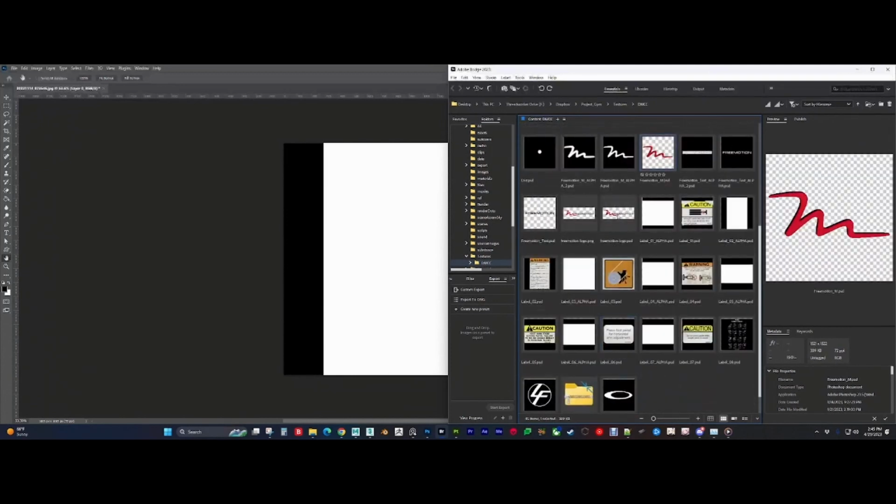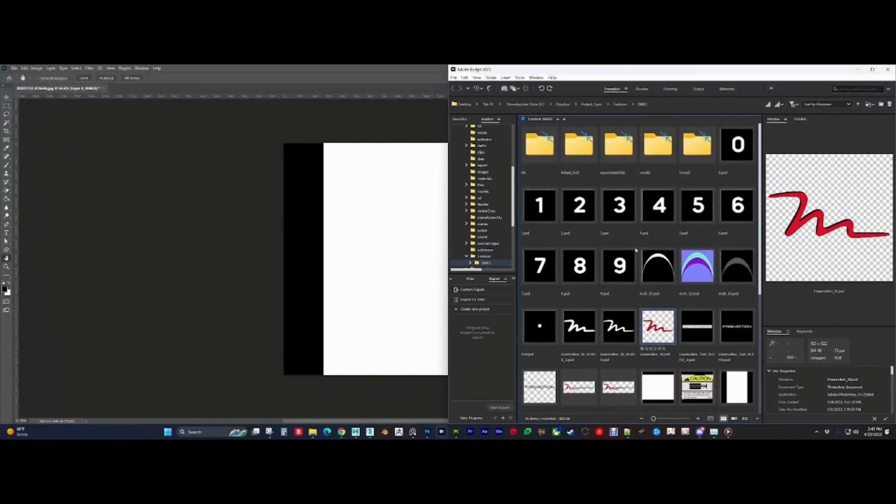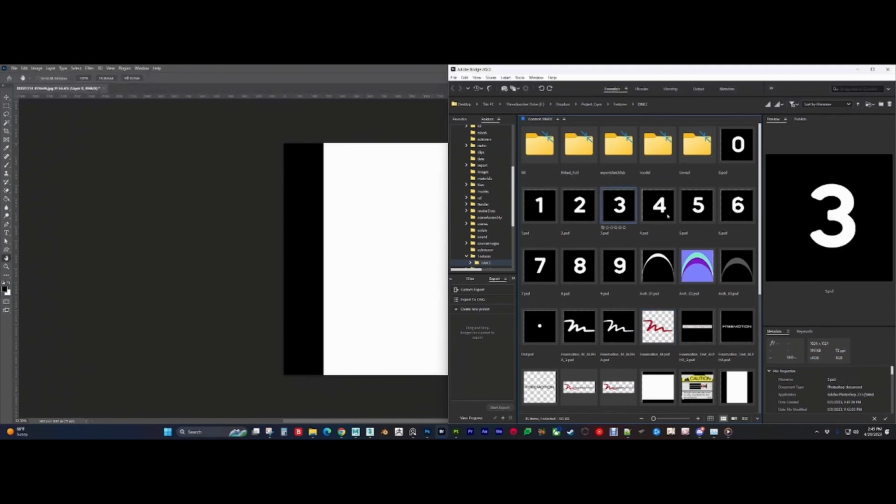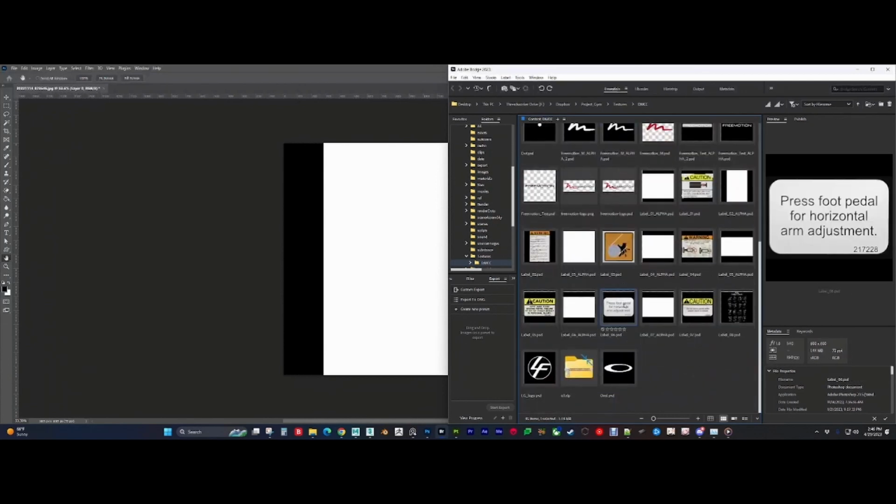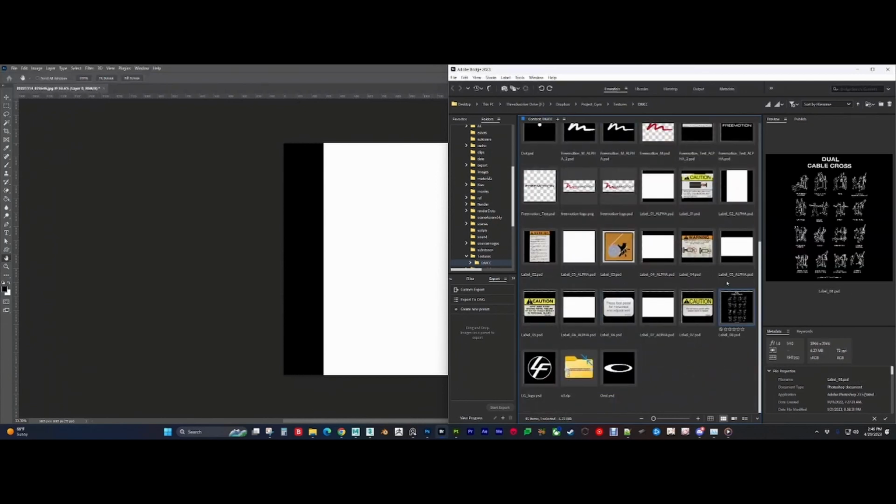You can see in here, I'm using Adobe Bridge just because it's easy to view all my PSD files. I make everything a PSD file just so I have flexibility. It's a non-destructive workflow, because if I need to make changes to certain textures, I can make changes and adjustments and save it, and then update it automatically inside of Painter, just using the update resources function. So one last thing I want to show is this texture here.